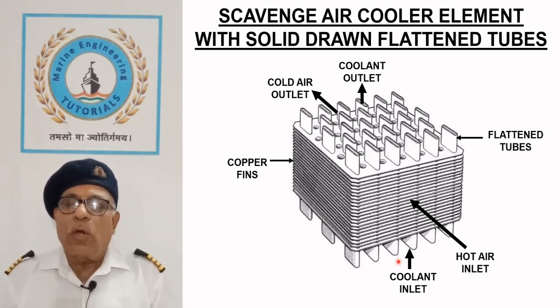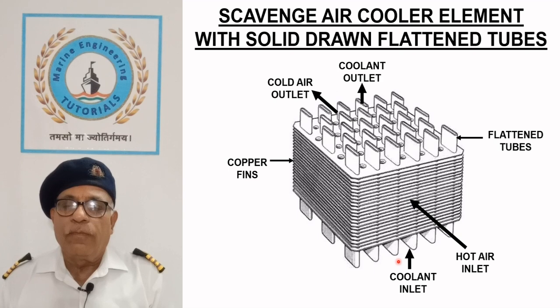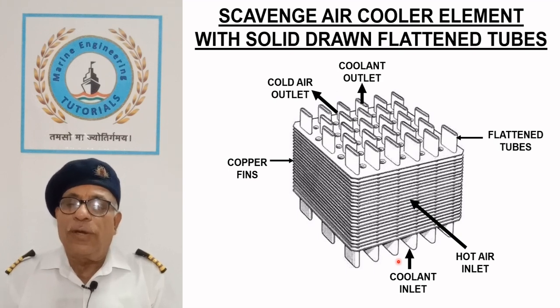Regular monitoring of scavenge air temperature provides a fairly good indication regarding the condition of the cooler and the requirements for its maintenance. The only attention that the heat exchanger requires is to ensure that heat transfer surfaces remain substantially clean and flow passages are generally clear of obstructions.